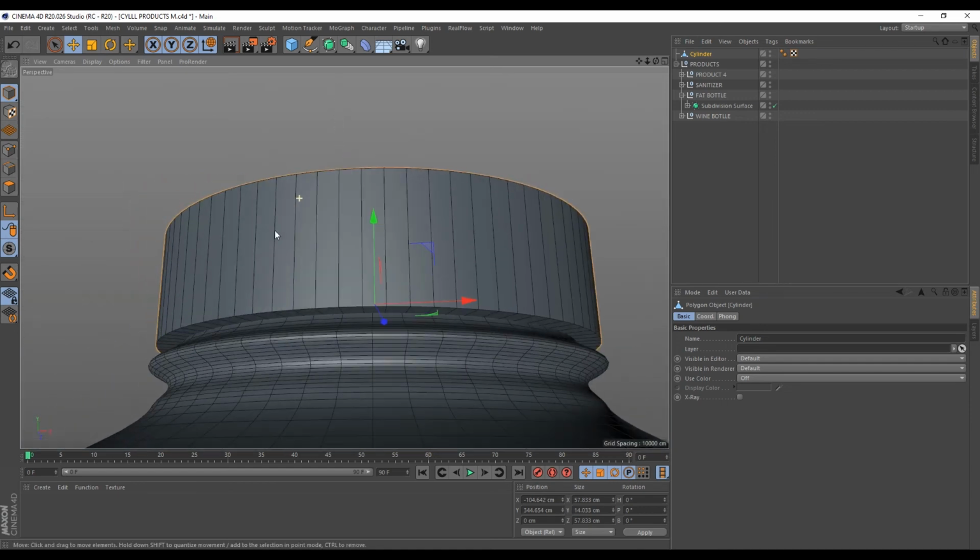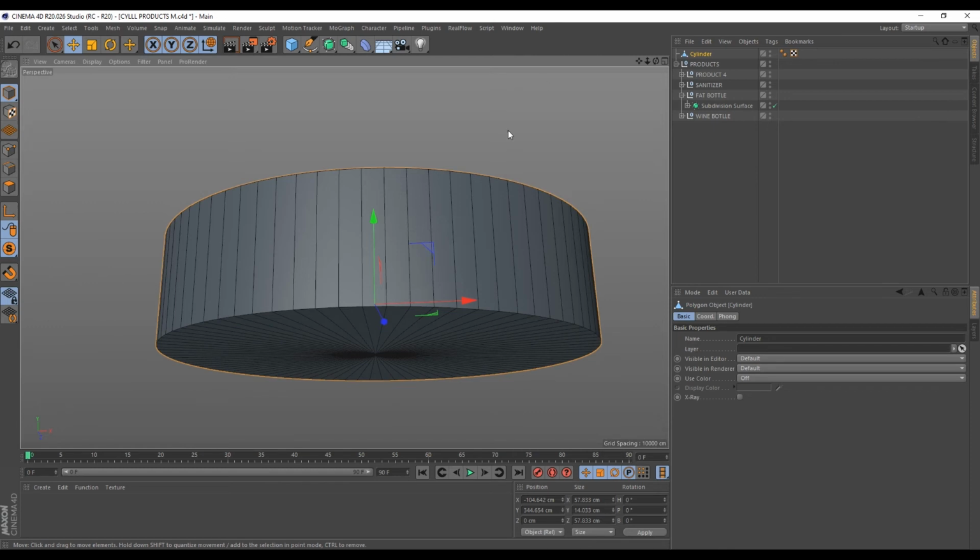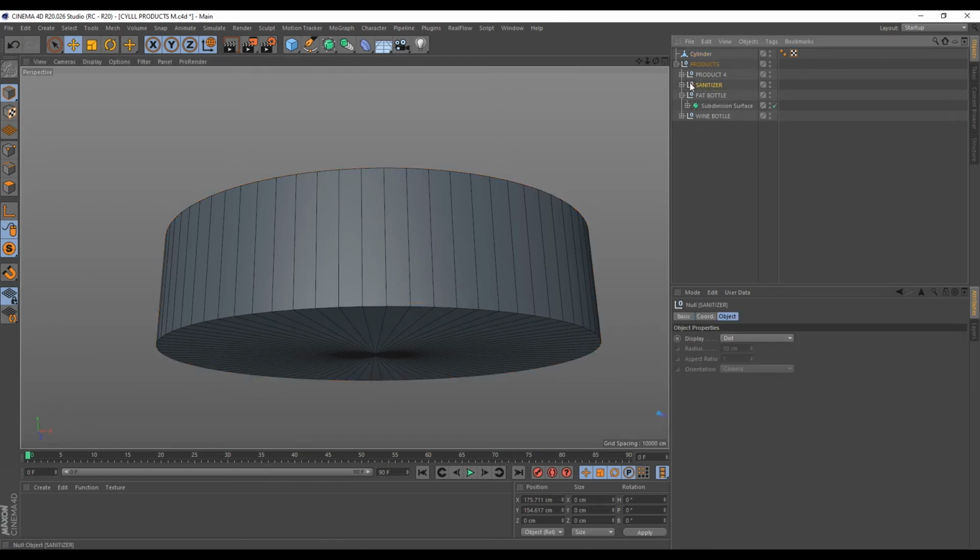So because I want to see the base of this mesh, I want to isolate this mesh and work only on this cover. So to do that, you can come here to your solo option. If you click and hold this down, to bring these options. So once you selected this object, you can select viewport solo single and that will isolate only this object. If you want to isolate a null, then once you click that null, because it's a group of objects, once you come to your options here, you select viewport solo hierarchy.